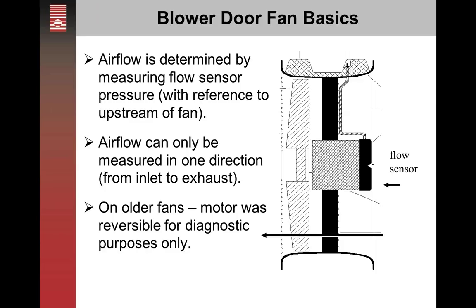Now, all of our fans that we currently make have flow in just one direction. You cannot reverse the fan motor, and the reason for that is that you can only measure airflow in one direction. We're measuring the flow from the flow sensor through the fan blades. If the motor has been reversed, the value that shows up is going to be incorrect.